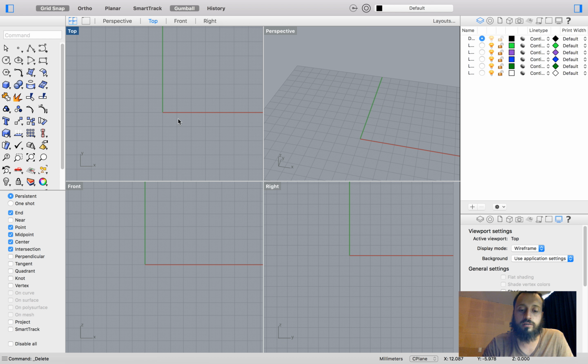There are going to be many options sometimes here that I can change, and that will allow me to modify the curve. For example, if I put the degree at 2, it should make it more square, or more, depends. Well, I don't see. If I select 1, you see it makes it a polyline. So there are different options for different types of commands we're going to work with. Okay, point, polyline, curve. Now we can start doing a circle.